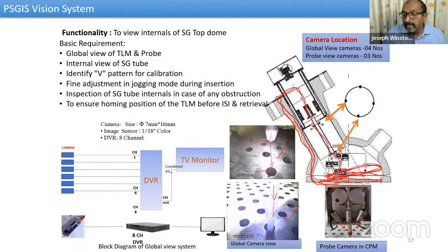That is precisely the reason we emphasized calibration of the system after deployment, the 3 point calibration. Instead of going for very stringent tolerancing, though we followed stringent tolerancing, some of the errors are not correctable, because the deployment module sends the system all the way down from top to here. If there is some flexibility here, it can lead to secondary effects, which will cause some bending on this slope. So this plane and this plane, we can never match them in practice.